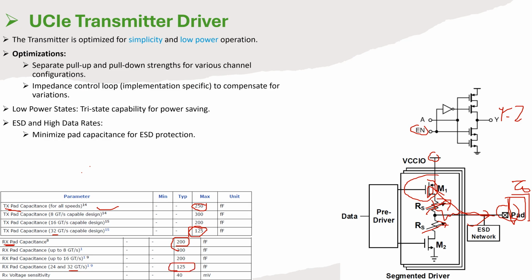We are able to achieve such a low capacitance because packaging technology is very advanced now. We used to use, sometimes 5 picofarad for packaging, and in older nodes we used to use 35-40 picofarad of pad capacitance. You can't even imagine achieving such gigatransfers per second with that big a load.